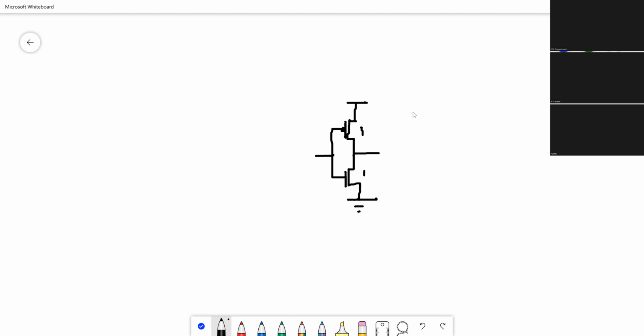That is what I have done here. This should have originally been 2, but I have made it 1, and this should have been 1. I have kept it at 1, which means that this is the critical transition. That is, the 1 to 0 is very important for this particular gate, which means that it is a low skew inverter.